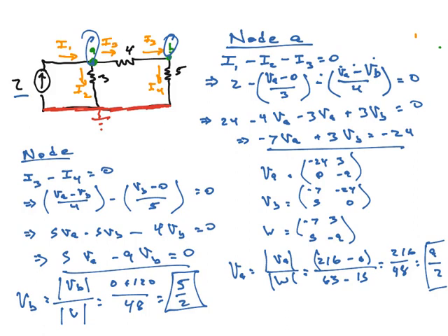Take that equation of I's. Any I's that you know the number for, because you know the current source or something like that, you plug the numbers in. All the ones you don't know the numbers of, you replace with V over R. How do you do the V part? Well, you take the V at one side minus the V at the other.